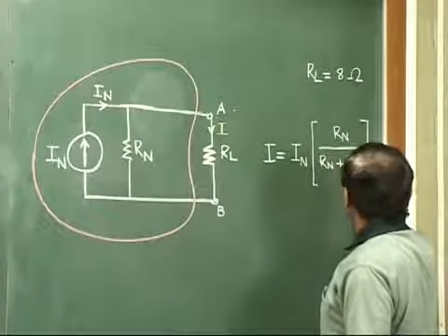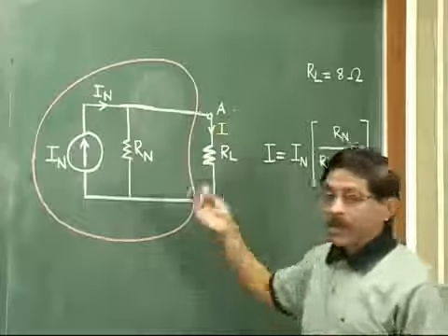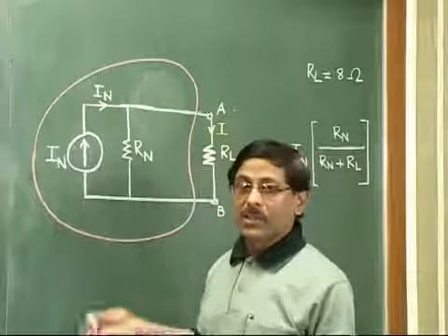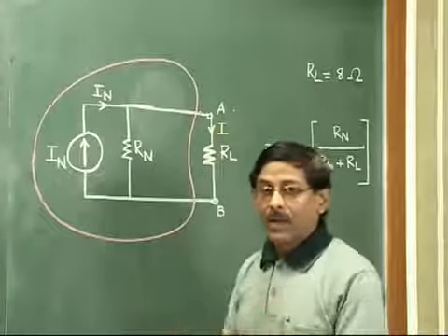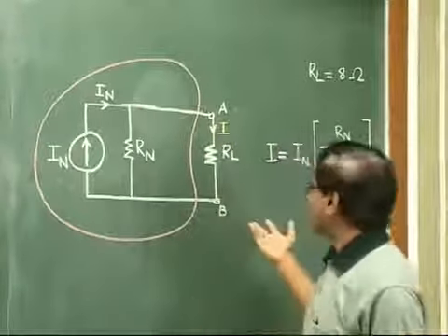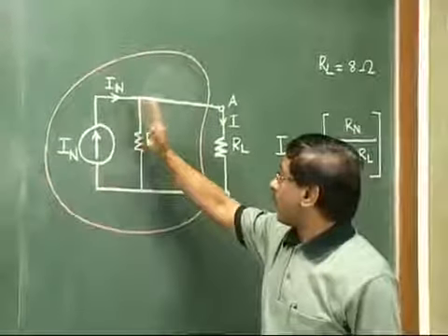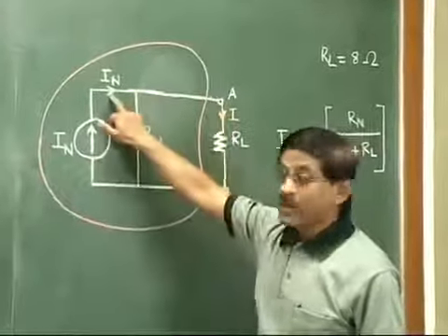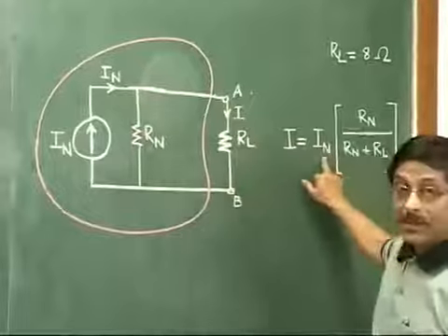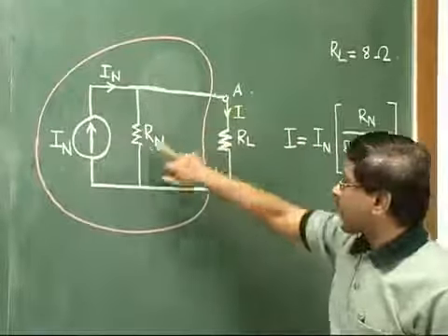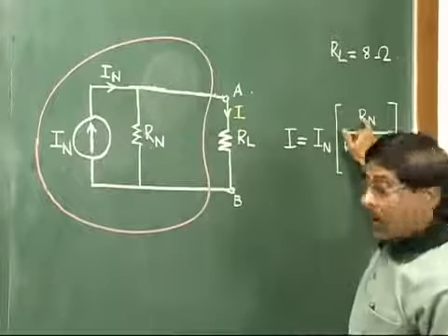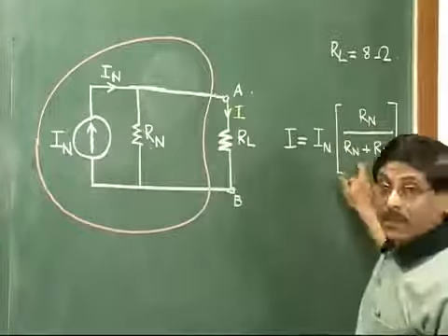Now this is a very fundamental thing that everybody learning electrical engineering courses knows, the current distribution into 2 parallel resistances. It is simply like this. The total current coming towards the parallel combination is IN, so IN is written here. But if we want the current in this resistor, then you take the other one in the numerator and the sum of the 2 in the denominator.